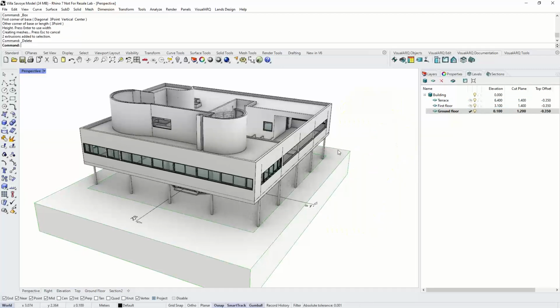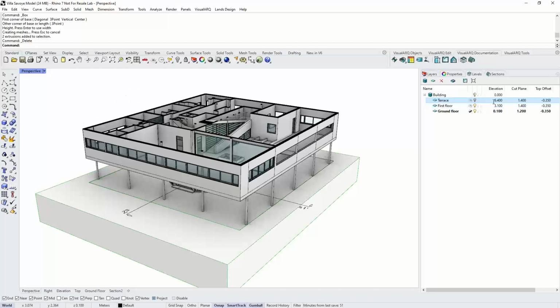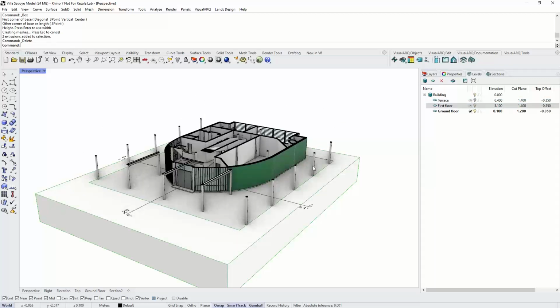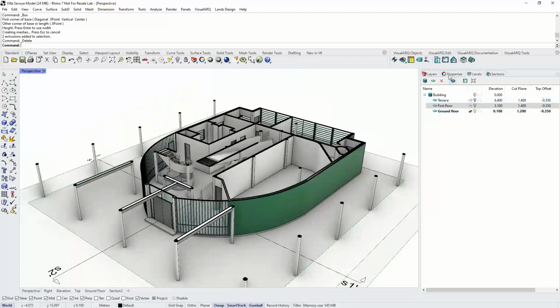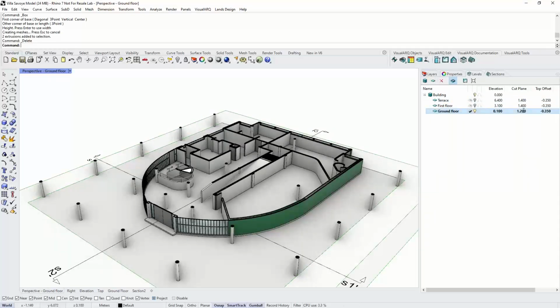Also, we can hide levels. Okay, just imagine that we have a clipping plane at the position of this construction plane, okay, of the level elevation, and hide everything that is above. So we can just hide levels very easily from here and work on the inside of the project very easily. Also, levels have a cut plane. So in case of the ground floor, if I activate it, this cut plane is located at this elevation in relation to the level's elevation, and it's usually the elevation that cuts through all the doors and windows.